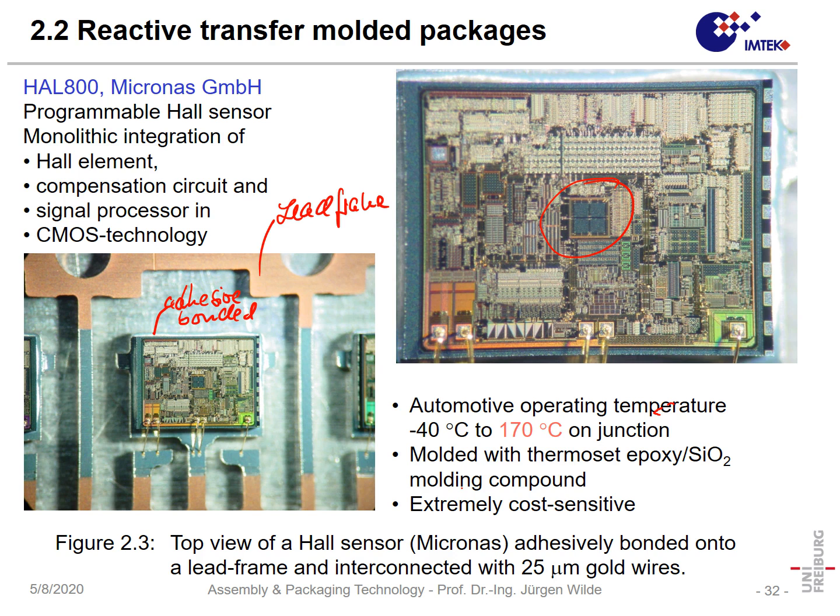And after we have that, we need wire bonds. And in the end, all of this can be coated with a plastic material, and so the device is almost finished. That technology is both for through-hole technology and for surface mount technology.